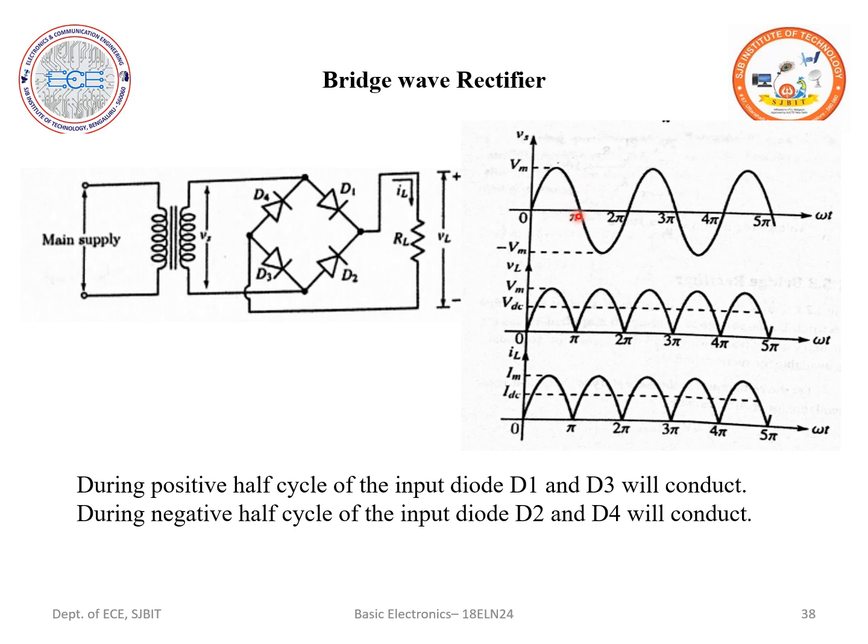When we give the positive half cycle as its input, the diodes which are opposite, that is D1 and D3, we can look at through the polarities across the points. Let me name this point as node A and this as node B. Once the positive cycle is applied here, the polarities across the secondary winding are going to be positive and negative, as shown here.